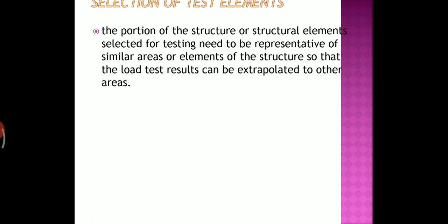Then selection of test elements. The portion of the structures or structural elements selected for testing needs to be representative of similar areas or elements of the structure, so that the load test results can be extended to other areas. So we have to choose the location of the load test such that it is representative of similar areas or elements of the structure.